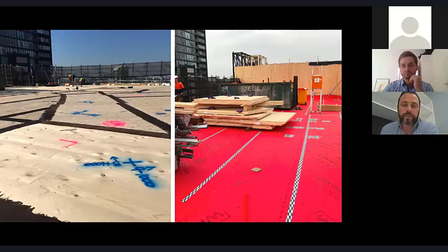So what Nathan jumped to here was some images of different waterproofing methods, where we looked at waterproofing just the joints, but also running a more breathable wrap. That's a Proctor wrap, pre-installed on the CLT, which works better, however more costly. And we needed to do that just to ensure that we can continue our fit out and not get too many water damage or water issue management problems on the project.